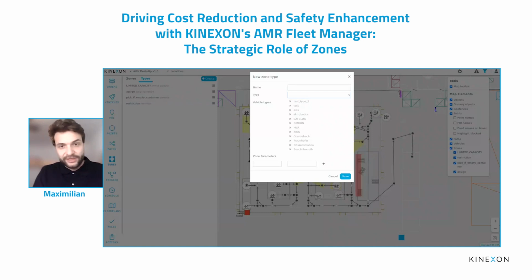Well, vehicles do obstacle avoidance; especially more modern vehicles can drive around obstacles dynamically and adapt a route around them. Well, you don't always want to do that. For example, if you have tight hallways where it could be complicated for them to get around each other, or they get stuck while trying to do obstacle avoidance because of difficult circumstances on the shop floor, you can activate or deactivate that behavior by setting a zone over that area that is sent to the vehicle, and the vehicle knows, okay, usually I can do obstacle avoidance, but maybe here it's not a good idea. So they don't do obstacle avoidance there. That's incredibly useful as well, because it is based on the actual position and not just on a graph.